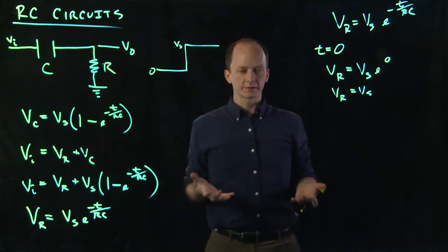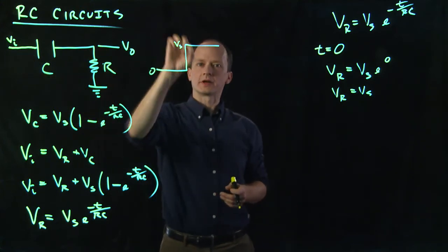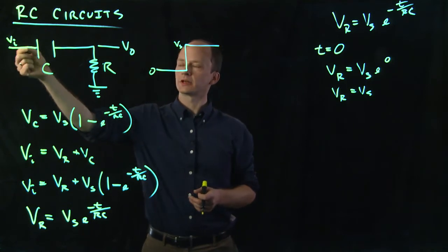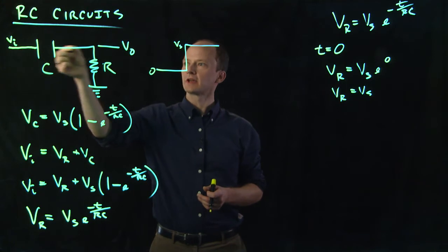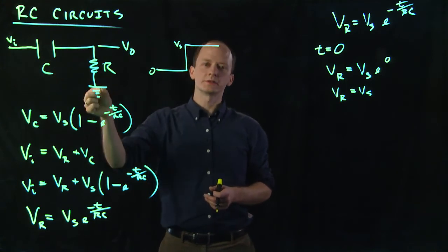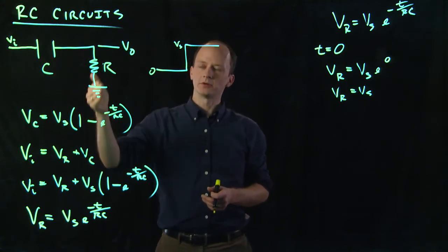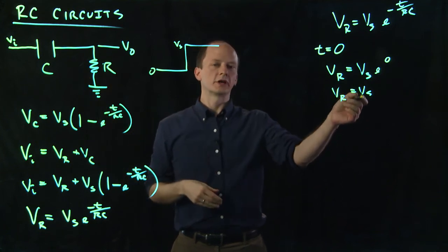Again, does this make sense? We have a very rapid transient. We have said before that during a transient, our capacitor is going to act as a short. So effectively, we just have a circuit with a single resistor, with the voltage drop only across this resistor. So that's what we're actually measuring.